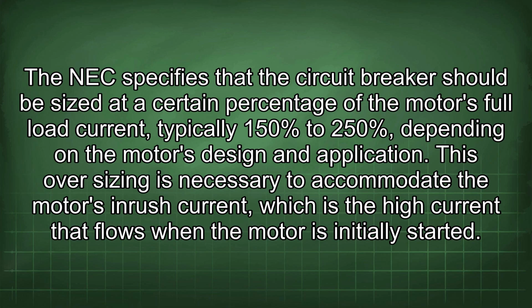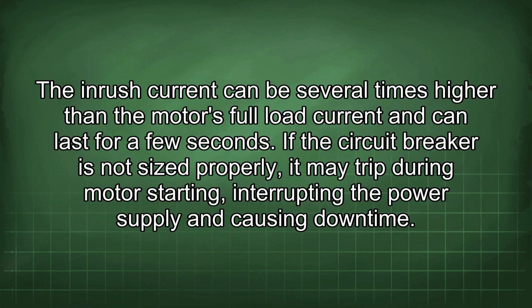This oversizing is necessary to accommodate the motor's inrush current, which is the high current that flows when the motor is initially started. The inrush current can be several times higher than the motor's full load current and can last for a few seconds. If the circuit breaker is not sized properly, it may trip during motor starting, interrupting the power supply and causing downtime.